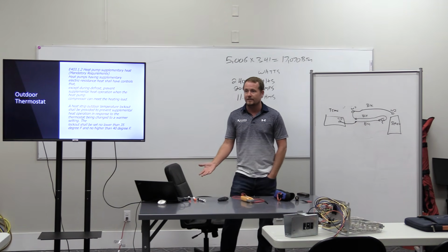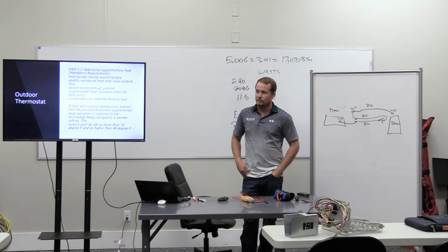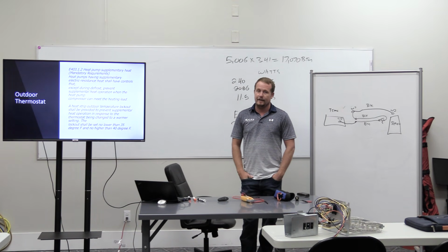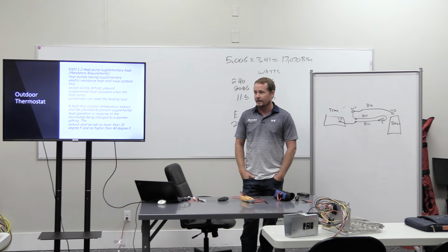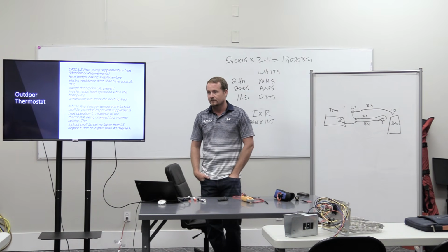In terms of energy savings, it's actually a pretty good idea because you really don't need to run heat strips when it's warmer than 40 degrees outside. And heat strips really do run up power bills pretty quick. And it's actually kind of nice too because it's another thing that prevents your thermostat from doing something stupid and running your heat strips stupidly, or just a loose wire.